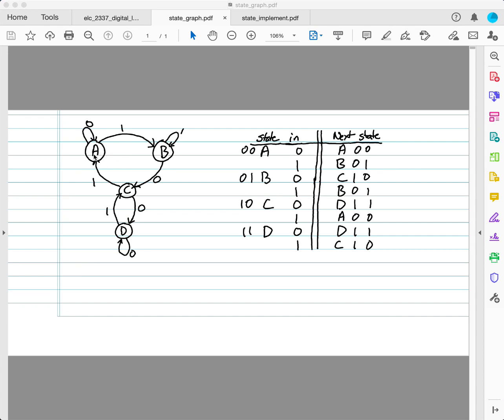And we do these names because you don't necessarily know how many states you want and how many bits and all the rest of this type of game. Sometimes you discover, oh, it would have been so much better if I had named this other state zero, or however. So there are different ways to reassign the values. There's nothing magic about which one of these gets numbered 0 and 1 and so on. There are different schemes. So rather than worry about that, we just give them letter names at first.